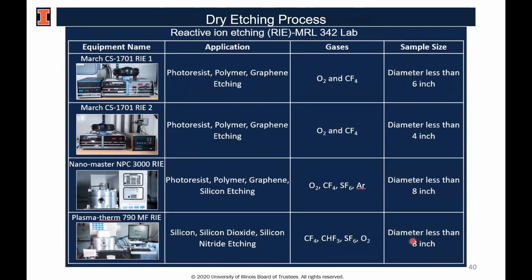Then there should be a counterpart, which is physical etching. The dry etching process is actually a combination of chemical etching and physical etching. For physical etching, the etching profile is no longer isotropic. On the other hand, it's anisotropic. Also, the physical etching can be controlled more precisely.